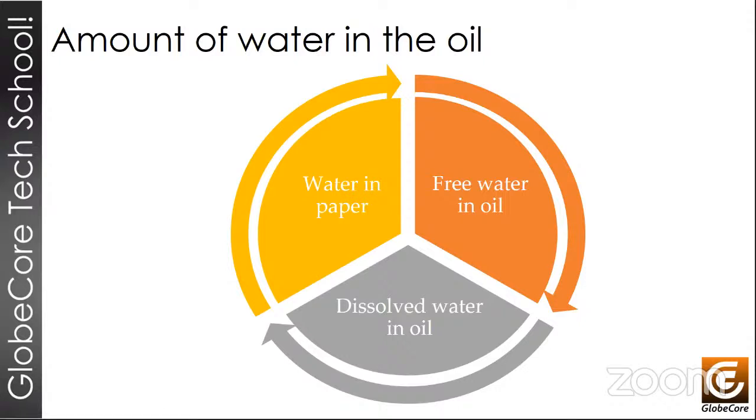And we must remember that water is also a catalyst. It promotes rather harmful chemical reactions. These reactions flow faster and easier, and that has a direct impact on the service life of the unit. We know that oxidation processes, for instance, occur much faster in the presence of water, and that paper is also seriously affected when water is present inside the transformer. And these are just two possible problems that can arise in the transformer when humidity is increased.